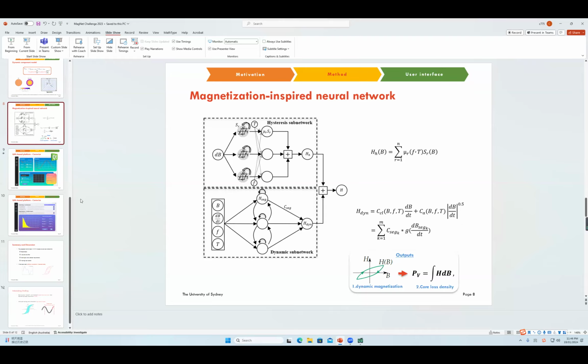And what do you think about, for example, the minor loop and the transient waveforms? I guess the main reason we did badly is we didn't put all mechanisms into our model. I've already tried a new version of my model, and we added some memory part like LSTM into the hysteresis subnetwork. The average error and even the 95 error improved much. So I guess that's the reason why we did badly in some materials.